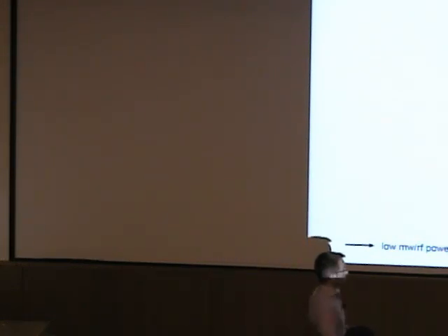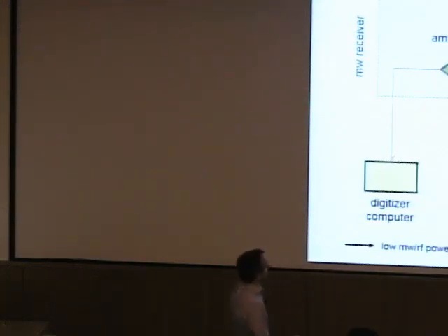Now, after the pulses are over, we can switch on the detector. And if you look here at the black arrows, that's a weak response from the sample. There's a little shutter in front of the receiver to make sure we don't kill it when we hit the sample with pulses. But once the pulses are over, a weak emission comes from the spins, gets amplified, detected, and digitized. So you have a powerful transmitter and a very sensitive detector or receiver to do this. And they're not operating at the same time. Either we transmit or receive.